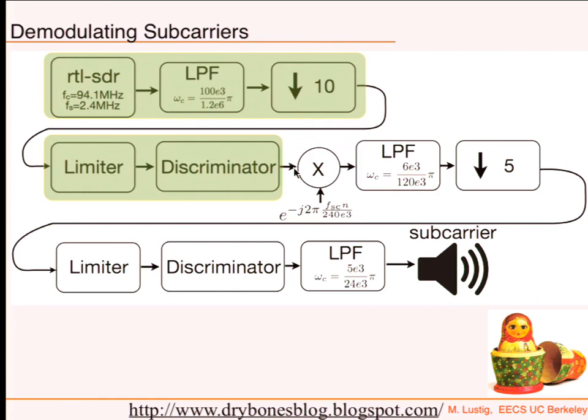We need to then demodulate one of those subcarriers to the baseband, which the SDR did for us before. Now we have to do it ourselves. So you're going to be demodulating by the subcarrier frequency, low-pass filter, decimate, then implement a limiter discriminator, then low-pass filter again, and then play it. Basically another FM radio after that. It's the same as this FM radio. So it's two FM radios implemented inside each other.